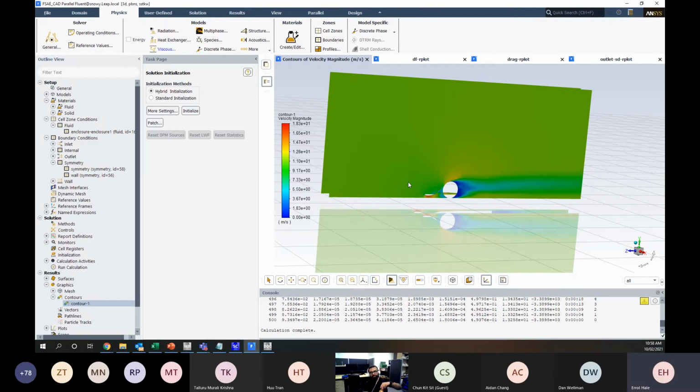It has enhanced wall functions that do similar things, but K omega is the most validated and the most highly recommended. But often you'll find that your research group at uni will have a preferred turbulence model, and that might be based on previous research that they've done where that model married up better with the solutions, and there's no right or wrong answer to it.